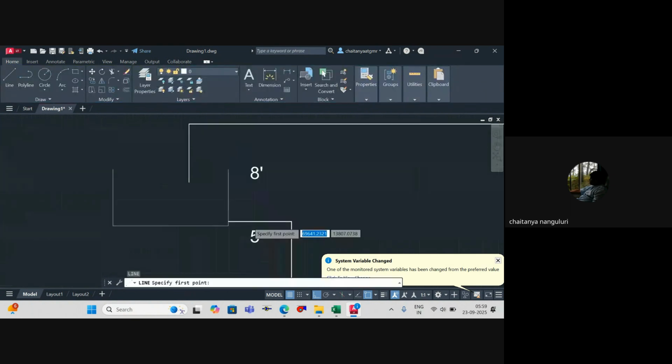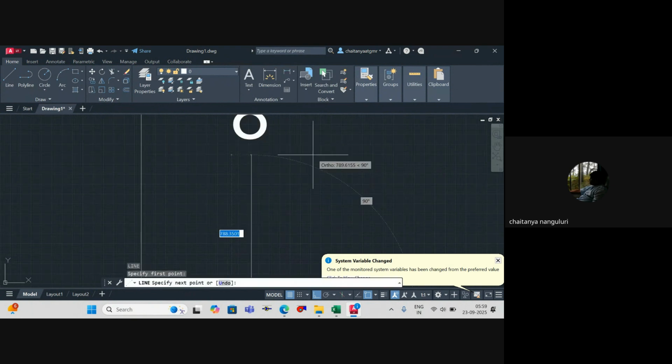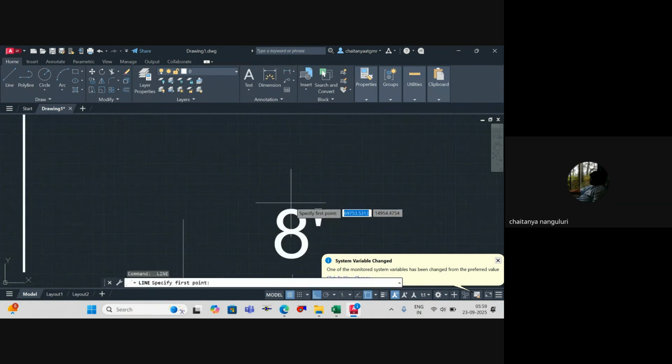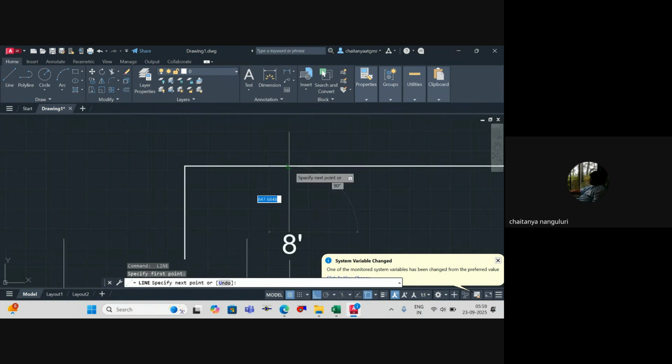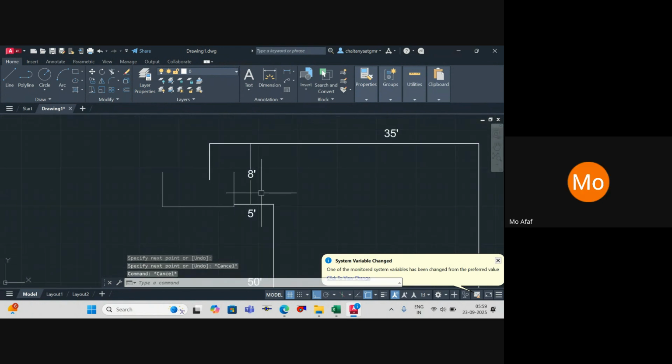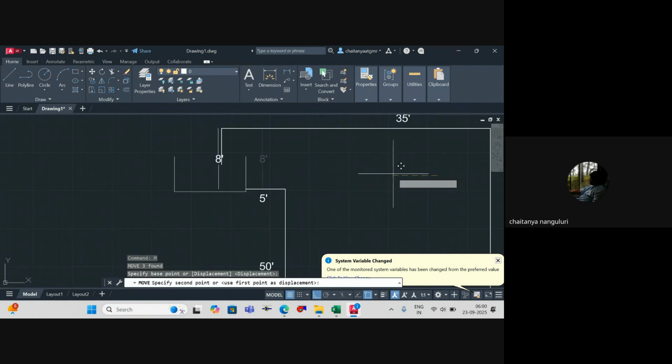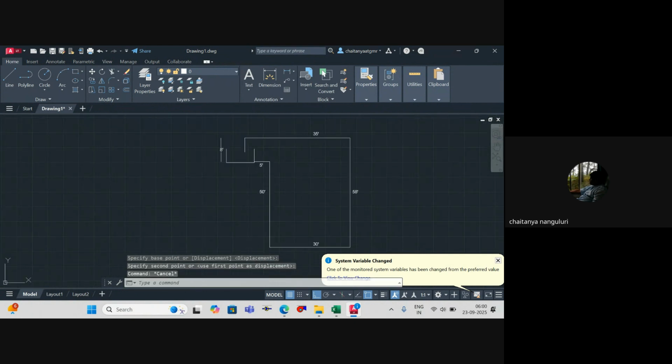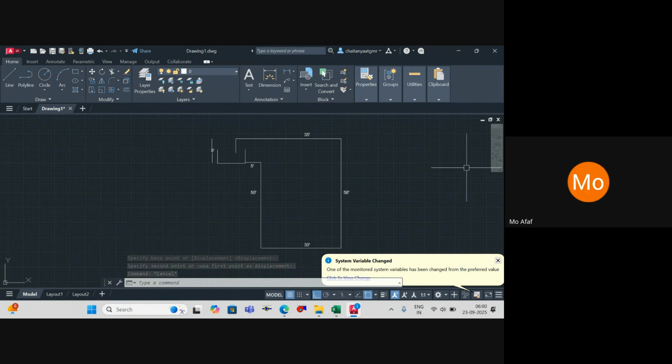This height is 8 feet, what I've represented. Am I clear? Okay, now you tell me, this height is 8 feet, let's say. Now you tell me what is the static head? 8 feet. It's obviously 8 feet. That's the difference between these 2 points. Understand? Because the circuit is entirely closed. Till here, the water will automatically come.